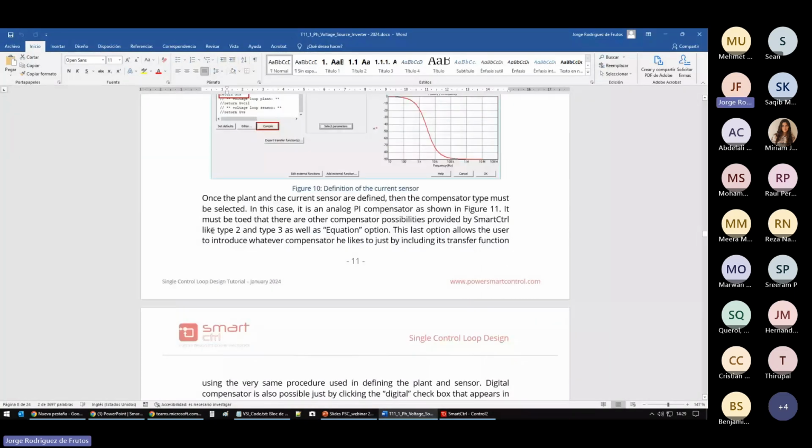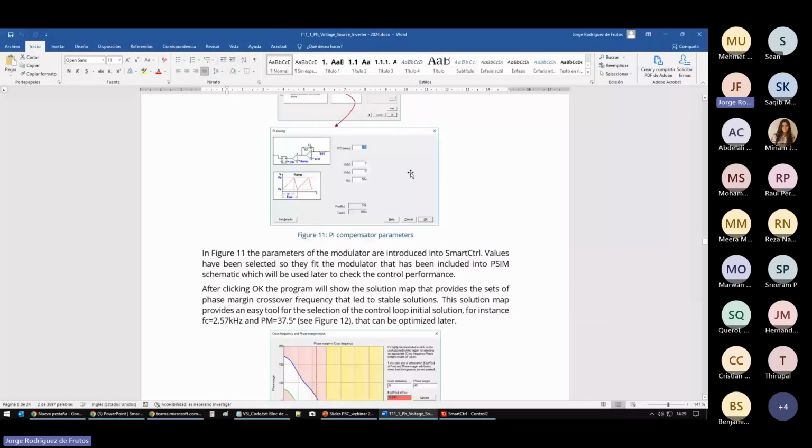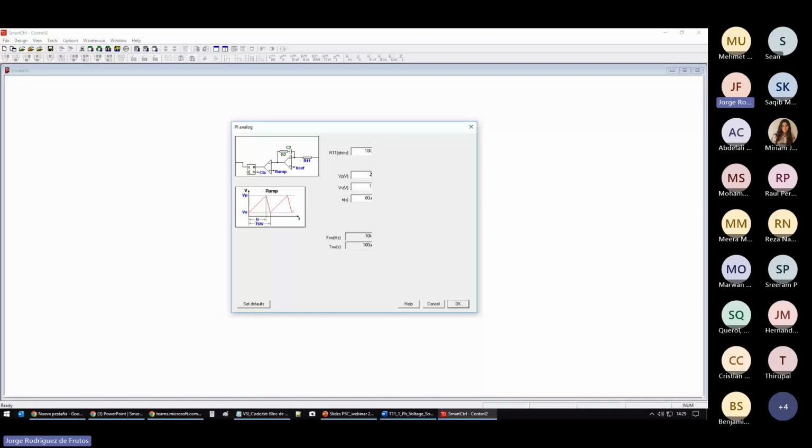So as you can see in here, we have 2, -2, and half of the period. This value in here is the rising time of this waveform. So if that is 50% of the total, so 50 microseconds is 50% of 100 microseconds, this waveform will be a perfect triangle. It will not be like a saw, just a perfect triangle.